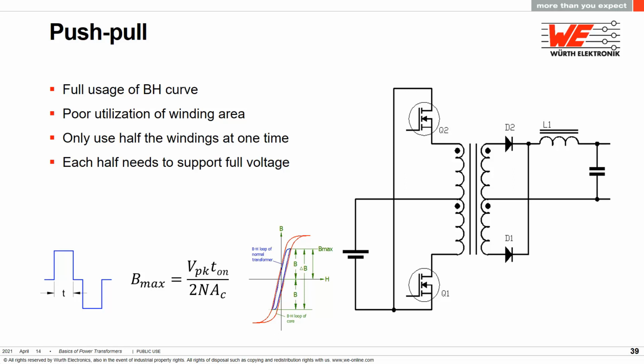When Q1 is on, D1 is conducting, and when Q2 is on, D2 is conducting. During the off periods, both diodes conduct as freewheeling diodes. Again, the entire secondary is a buck regulator.